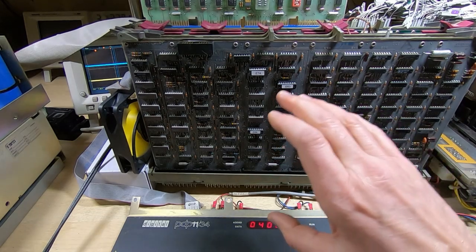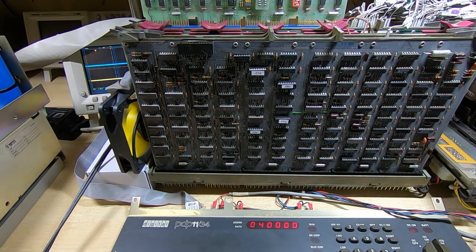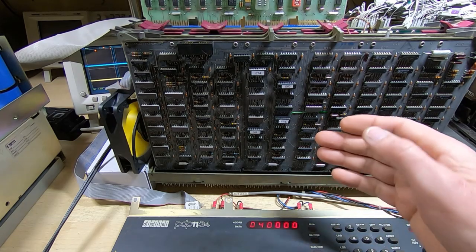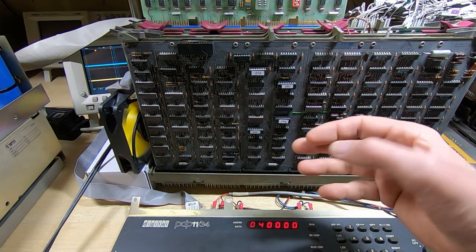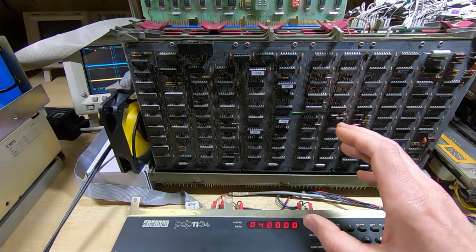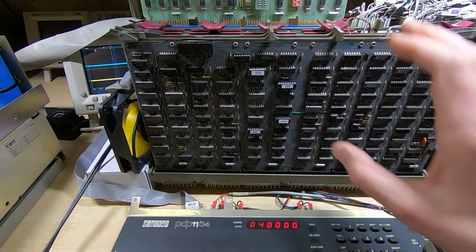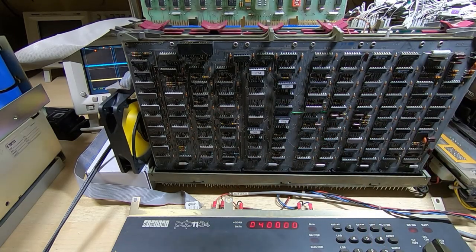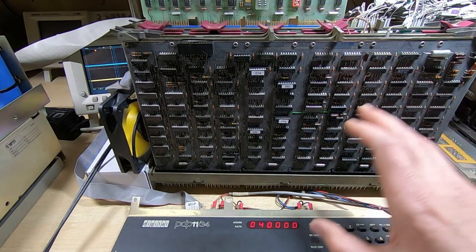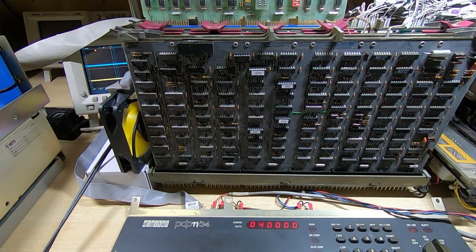but what I can do is work my way through them, try each command in turn, try various values, and then we'll see where it fails, and by the time we've done all this we should have a good idea as to what particular function is failing. Once we know which function is not working, we can then start looking into the control electronics in more detail. So rather than just looking at everything, we can focus in on the bit that's responsible for that particular function. And as I say, by the time we get through all the various functions and commands, we should have a good idea as to where the problem lies and how to go about fixing it.